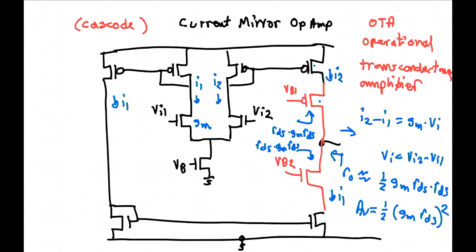And then we've got to put in Miller compensation, and then that makes it unstable because of the right half plane zero, and then we've got to put in lead compensation and stuff. Here, we just put in load capacitance, and that is essentially your compensation capacitor. Well, it is your compensation capacitor. So the capacitor here, CL, so that's Vout here. This is also your compensation.